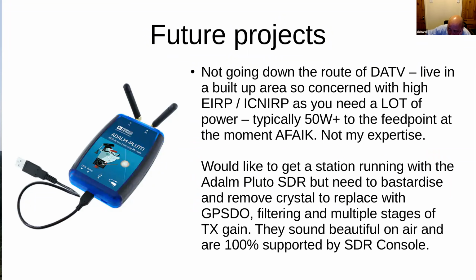You put 50 watts into the dish at the feed, and given the gain of a dish, it gets into the realms of very scary amounts of EIRP, and with the ICNIRP concerns that we've got at the moment, it's something I don't really want to go down the route of, and I haven't got the kit. It's not something I'm personally that interested in doing, but obviously your mileage may vary.